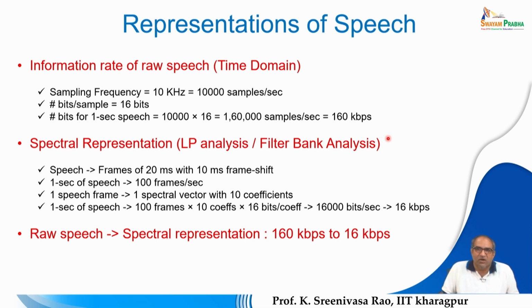Since we have 16 narrowband filters, each narrowband has a bandwidth of about 200 to 300 hertz, so that the 16 filters altogether can cover a range of around 4 or 5 kilohertz.